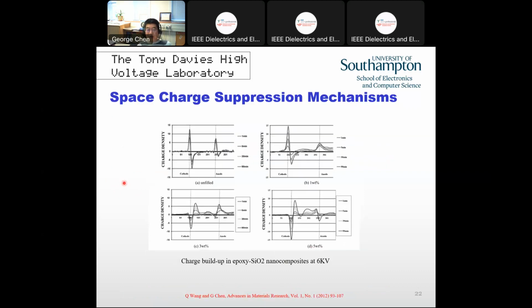In the early research, people also proposed that, potentially especially in the epoxy resin system, ionization may occur, and so the charge injection and the ionization may neutralize each other. As a result, less charge is observed, and therefore they proposed what we call the cancellation of the ionization and the charge injection.